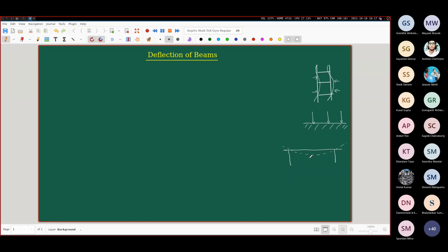So a lot of different design considerations and design cases have to be kept in mind for the design of beams. It has to be designed for strength, meaning the stresses should not be too high so that it doesn't break apart. Furthermore, the deflection also should not be too high, otherwise it is a practically useless beam. It's still standing, but you can't travel on it.